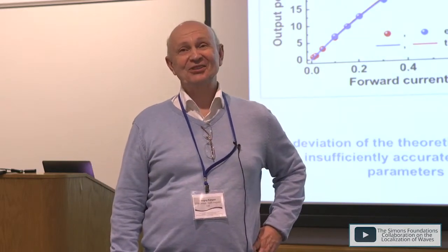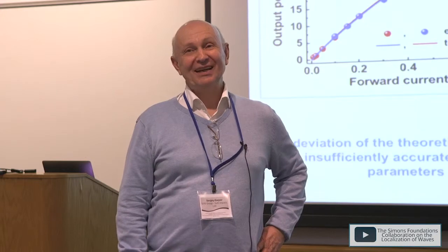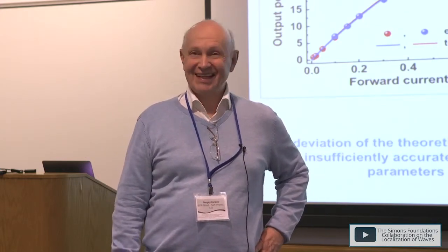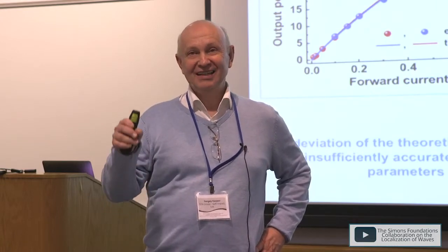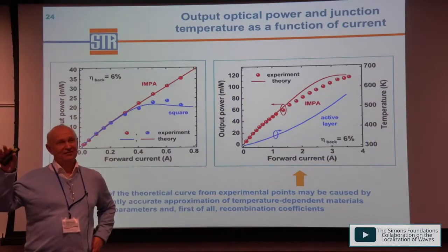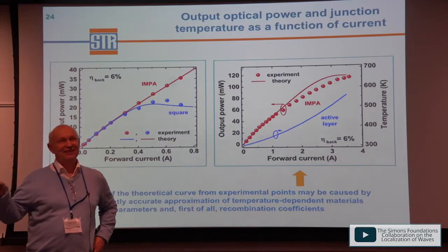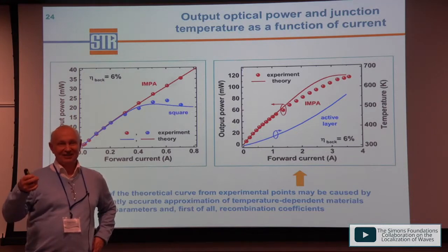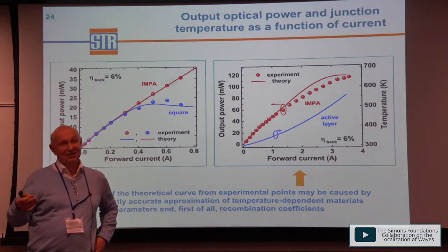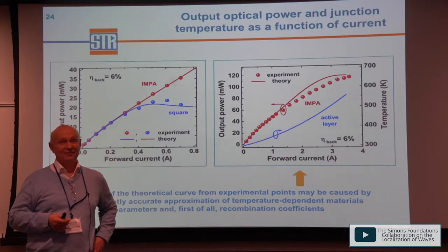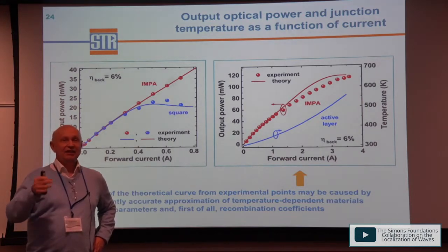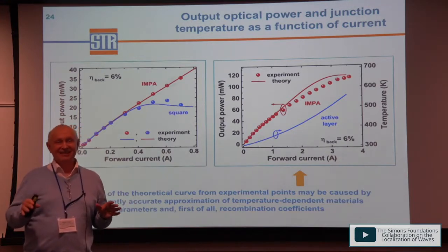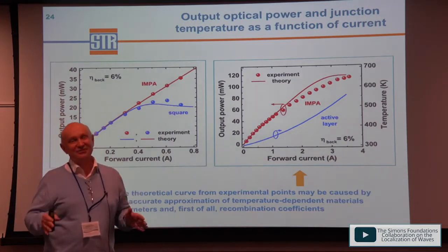Speaking about the destroyed quantum well, I meant the indium gallium nitride system, first of all. Because in this case, there are many dislocations. There are also very specific defects, like V defects, and so on. So actually, when you grow the indium gallium nitride quantum well, it's better to use the multi-quantum well structure. In general, if the growth issues are overcome, in this case, the single quantum well is as effective as the